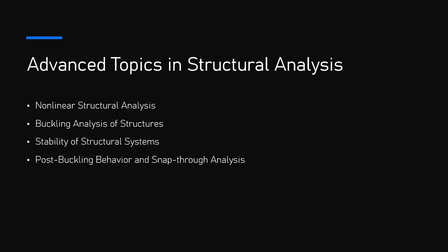3. Contact and boundary condition nonlinearity. Nonlinear contact. This occurs when parts of the structure come into contact or move apart during loading. For example, joints, supports, and interfaces between materials can experience nonlinear behavior. Frictional effects. Frictional forces between surfaces can introduce nonlinear behavior, especially when sliding or separation occurs. Friction models are often included in nonlinear analysis to simulate this behavior.